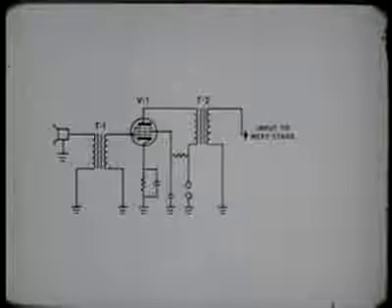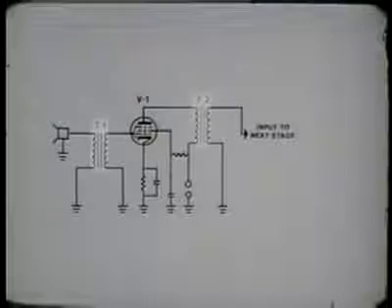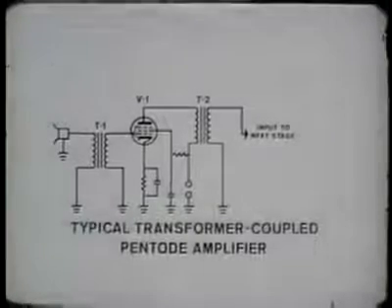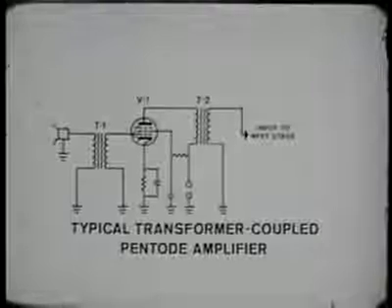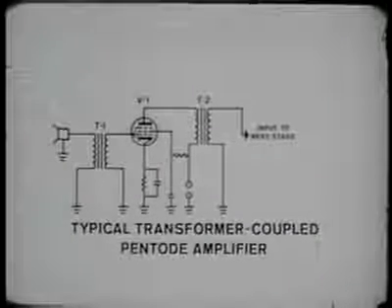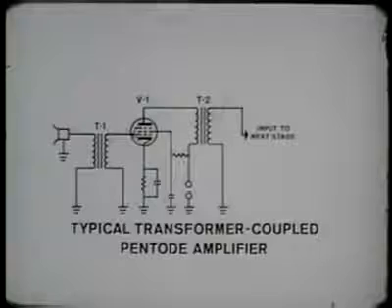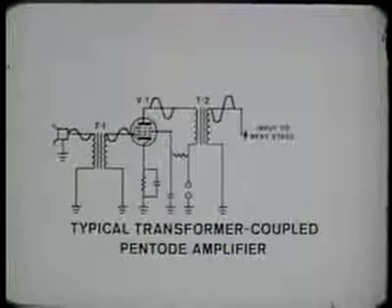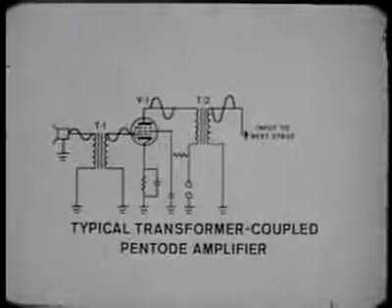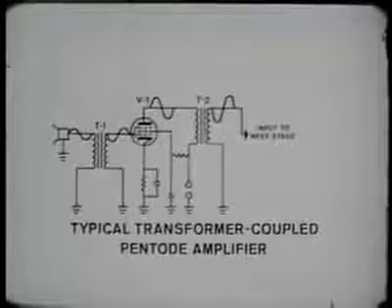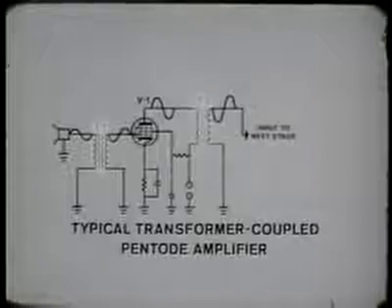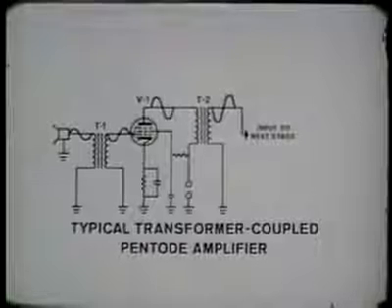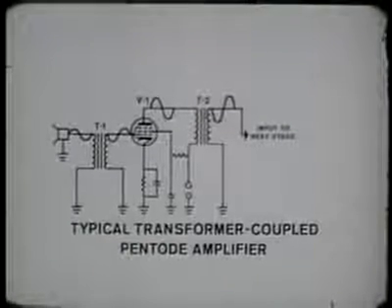An amplifier circuit using transformers as coupling elements is called a transformer-coupled amplifier. This type may be used either as a voltage or power amplifier. When used as a voltage amplifier, transformer design can permit stepping up the voltage between amplifiers. One advantage of transformer coupling is that at lower frequencies, the step-up characteristics increase the voltage to a point where fewer amplifier stages are needed.